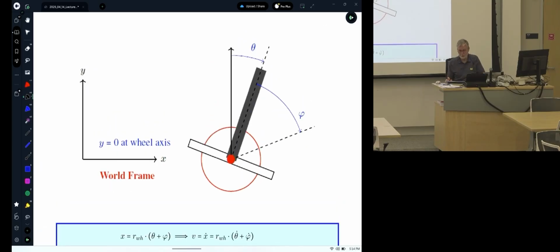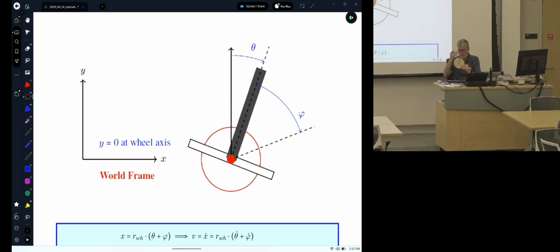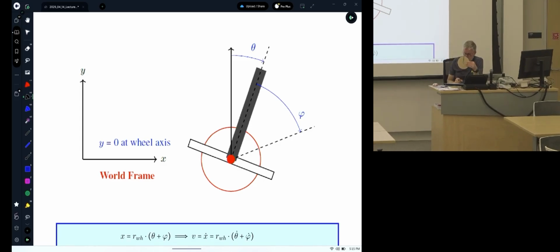Okay, so here's the coordinate system we're going to use, on one big bad Segway. The lean angle is theta, and then how much the wheel rotates, that's called phi. So there's an encoder here. The encoder is mounted to the motor that is mounted to the base of the Segway, so it can measure the rotations, potentially through gearing. That encoder will have a 0 someplace, and so we'll just take that as our nominal equilibrium point.